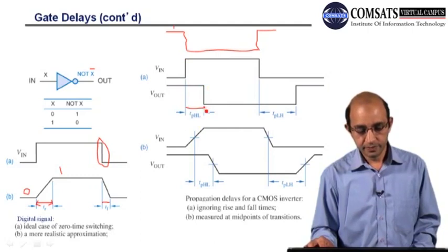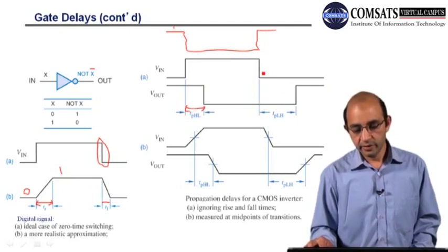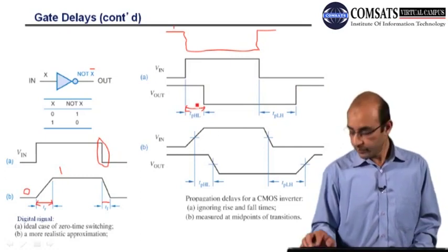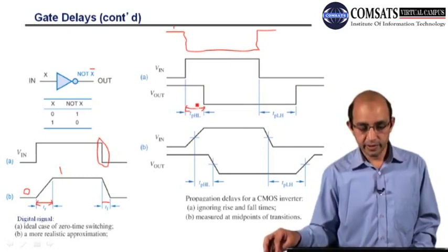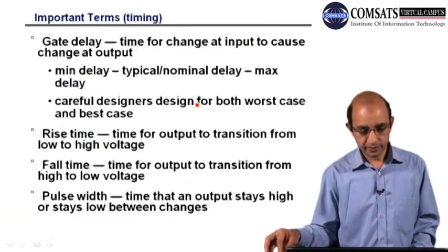So this is the delay. Similarly, here you can see that this becomes 0, so the output has to be high here, but there is no immediate response. You can see that we have a greater time when we are having propagation from low to high. So this is the physical, or graphical, interpretation of these sort of gate delays, and they are very natural.